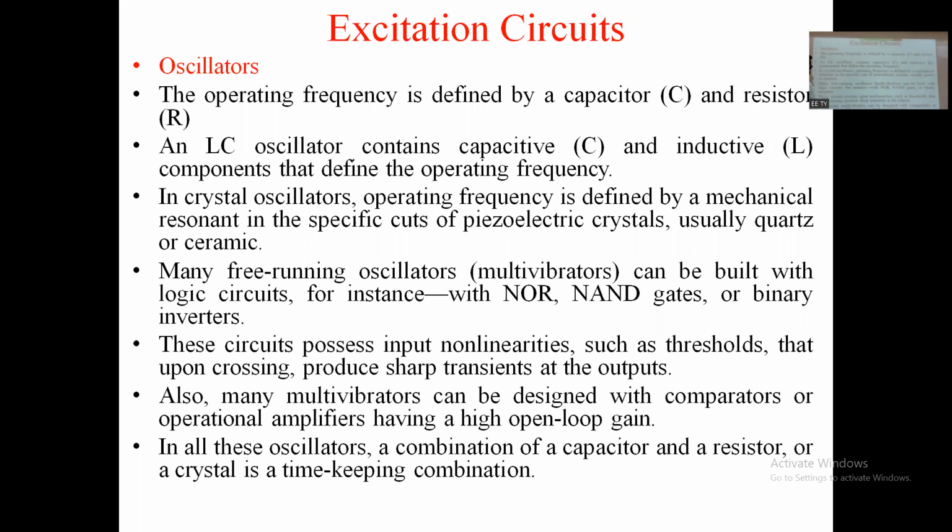In a crystal oscillator, the operating frequency is defined by the mechanical resonance in the specific cut of a piezoelectric crystal, usually a quartz crystal or ceramic crystal. Many free running oscillators like the multivibrator can be built with logic circuits, for instance using a NOR gate, NAND gate, or binary inverter. This circuit possesses input non-linearity,